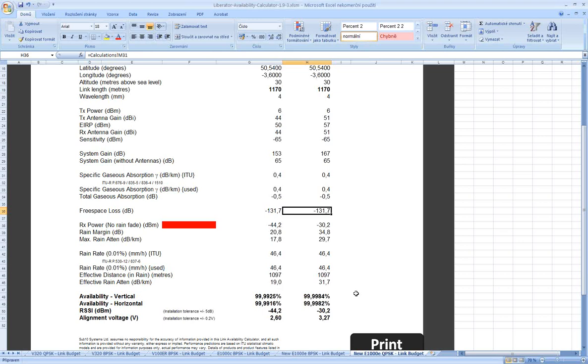But keep in mind, this calculation includes some margin to provide link availability for lifetime, and you have to be in some range around this value. If you are totally out of range, like 3-5 dB better or worse, you have to investigate why the signal is so different.